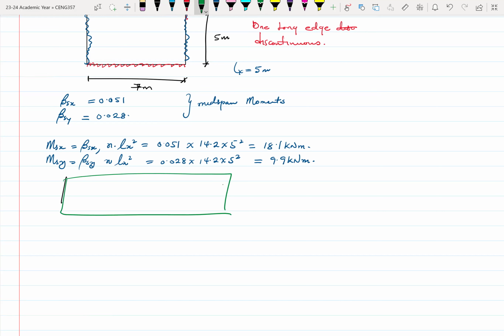So from here, you can find your K values, KX, KY for the different K values. Then also find your corresponding AXX and then AXY from here. Then you can use that to pick the rebar size and all of that.